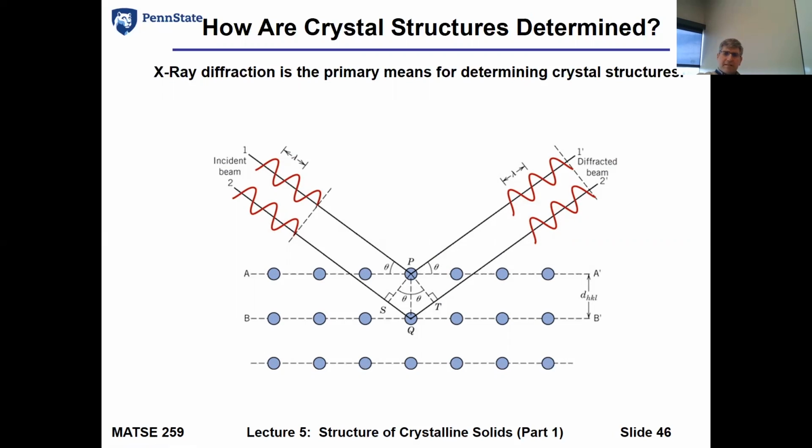The first thing to think about is wavelengths. We know light has a wavelength, we know there's infrared, we know there's a whole electromagnetic spectrum where different waves have different wavelengths and operate at different color schemes in the visible light range and the IR range. But in order to really get in between these atoms, we need something with a fairly short wavelength. X-rays do an excellent job of penetrating these structures, rather small distances into them, and they allow us to identify locations of crystals and what those crystals are through what we call characteristic wavelengths.